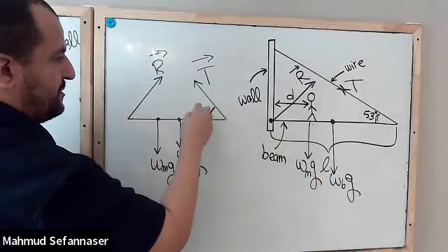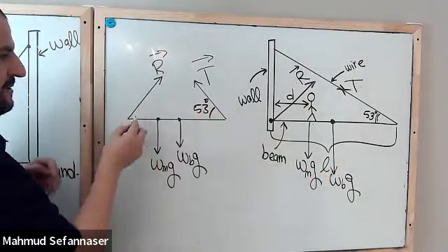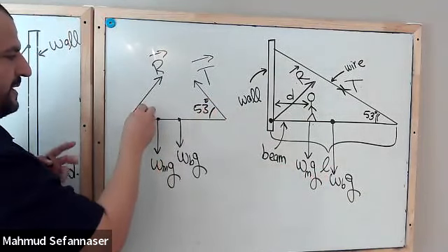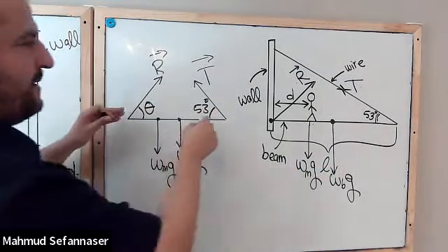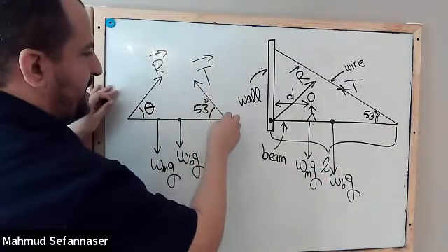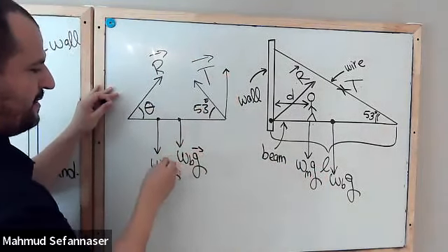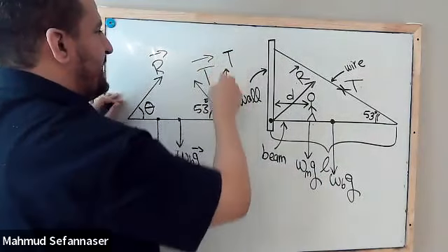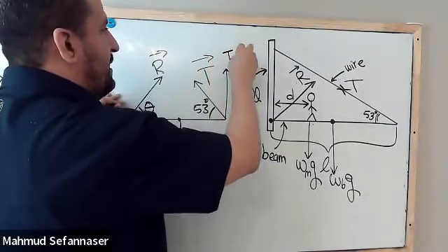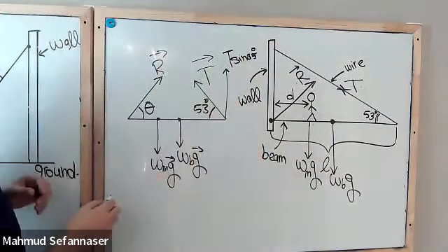So we are lucky to have 35 degrees from here, but we don't know the angle right here. So I will keep it just theta. And now I will decompose these forces. So upward, I will have here T as a magnitude, sine 35 degrees.